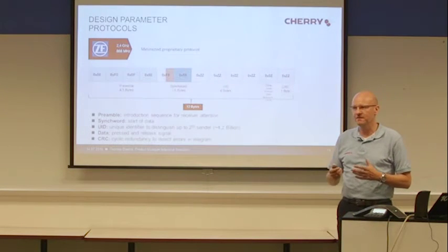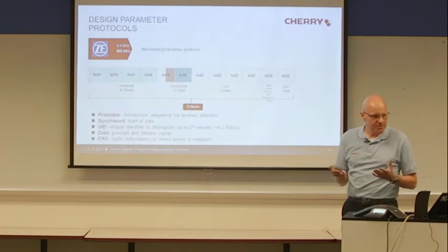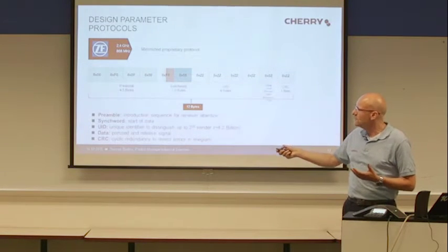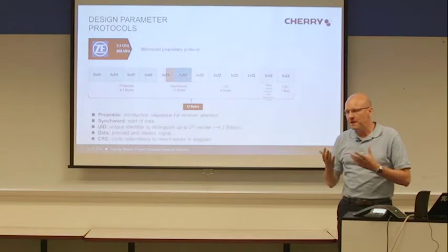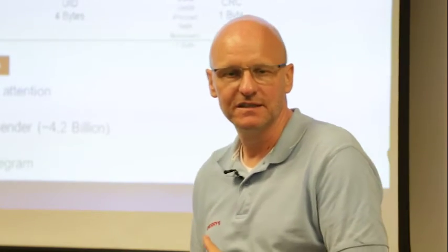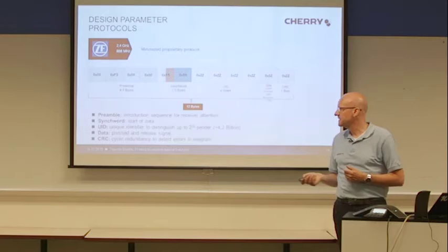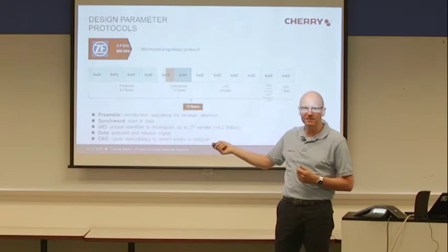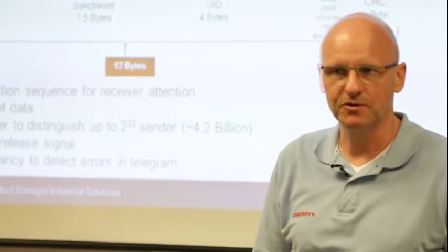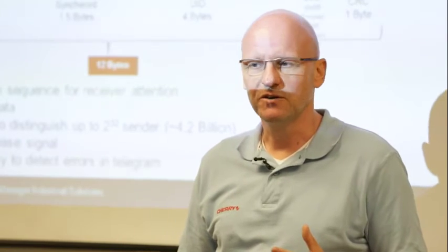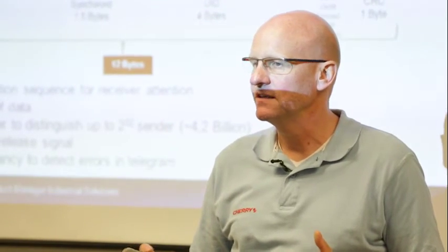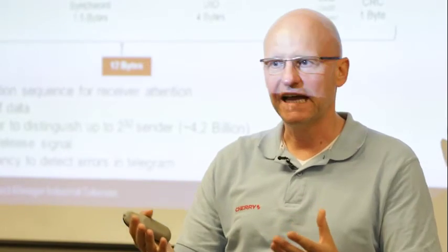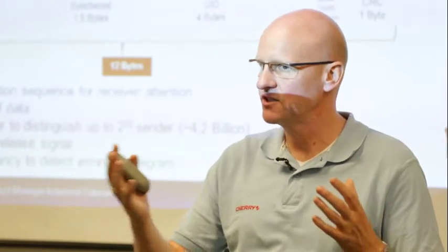And this is also a physical regulation of RF. You need a special design of your RF protocol so that it works over the RF channel, so that receiver and sender understand each other. For example, at first you need a so-called preamble. The preamble is the introduction sequence of an RF protocol. When the sender sends out an RF signal, the receiver catches all the signals on this RF channel.